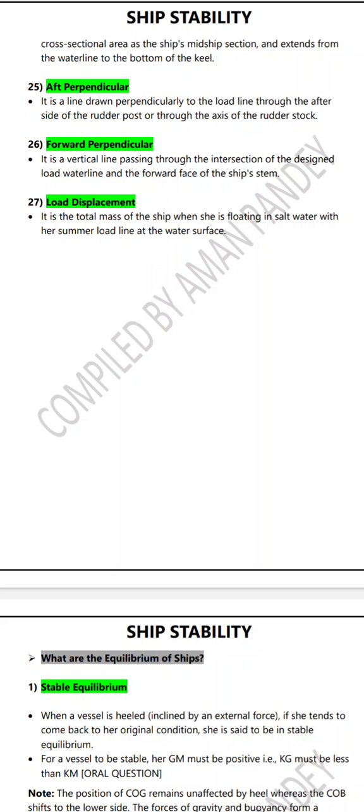Load displacement is the total mass of the ship when she is floating in salt water at the summer load line. Forward perpendicular is the vertical line passing through the intersection of the design load water line and the forward face of the ship's stem.